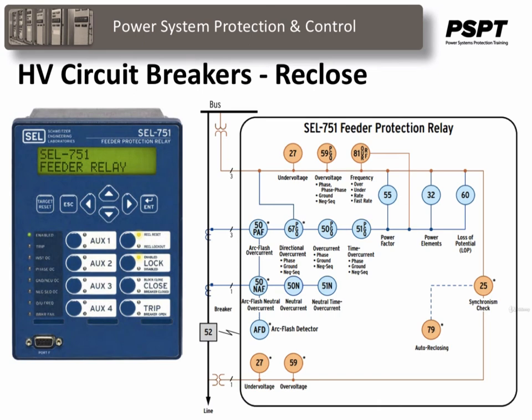As I said before, the CUH90 relay is definitely an old school relay and has a singular function, that is to provide reclosing for the breaker. A lot of relays now that are coming on the market are almost one-stop shopping. They are multitask and multifunction, and such is the case with the Schweitzer relay, the SEL 751 relay, which I'm only introducing here. It provides feeder protection in the way of overcurrent and power flow, and you can see all the functions that it does there.